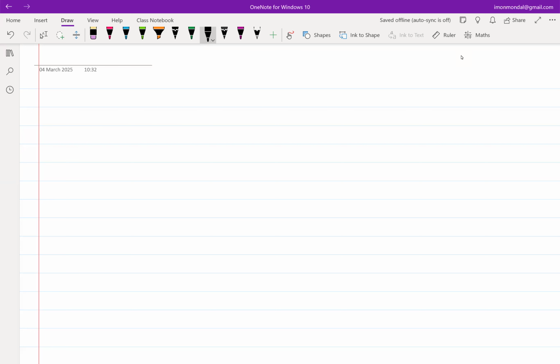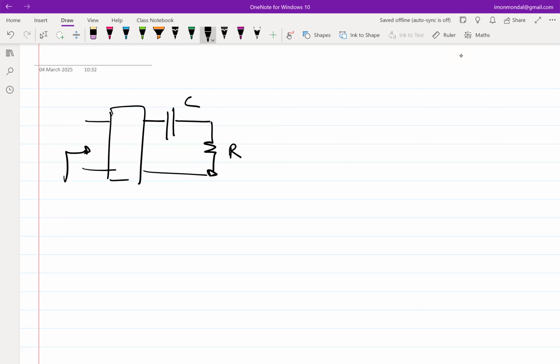So the question, if I recall, was this. You had a resistor and a capacitor, and you were asked to put something inside the box so that the resistance looking here was 4 times that of R, or some multiplying factor of that of R, at some particular frequency, not across all frequencies. And the constraint was, in this box, you can put either R or an L or a C, but only one element, okay?